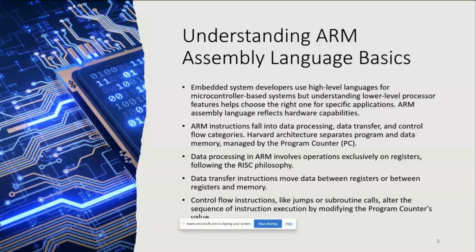In the previous sessions, we have discussed von Neumann and Harvard architecture. Can any one of you tell what the Harvard architecture is? Anyone, please. Harvard architecture. Yeah, in Harvard, data is stored separately, and for instructions there is a separate memory. Yes. So in the Harvard architecture, common in modern microcontrollers, there is a separation between program and data memory. Instructions reside in program memory, while temporary data is stored in data memory.